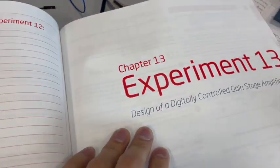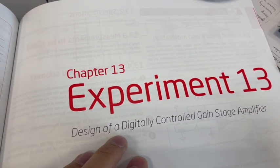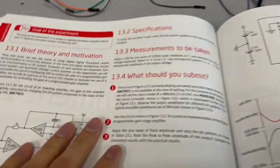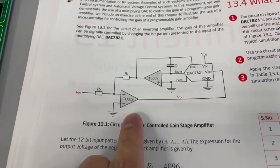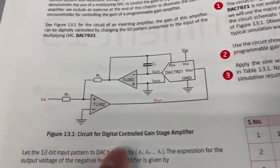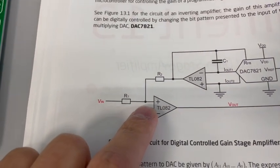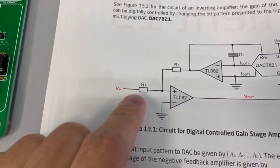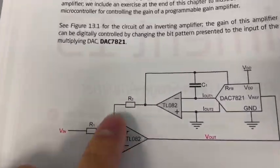So go to your lab menu, go to chapter 13, find experiment number 13, the design of the digitally controlled gain stage amplifier, and please follow these instructions. You have to connect two op-amps and your digital to analog converter as seen in figure 13.1. Connect the first op-amp with non-inverting input resistor R1. Choose R1 as 1K and choose R2 as 2K.